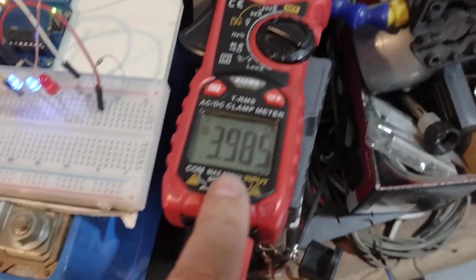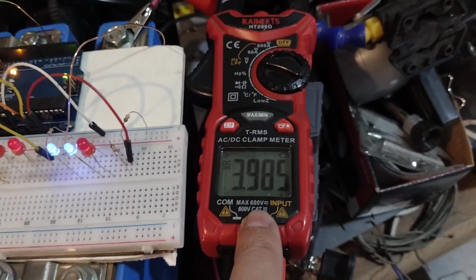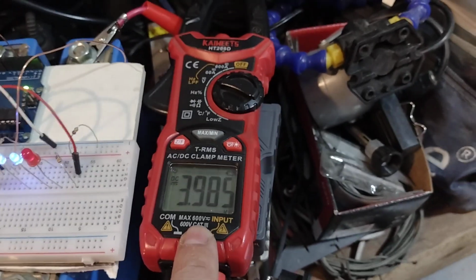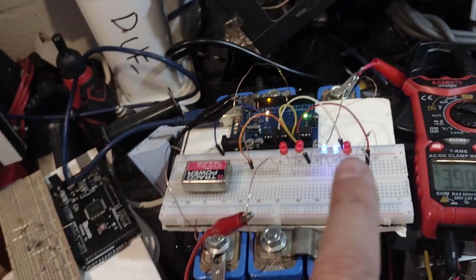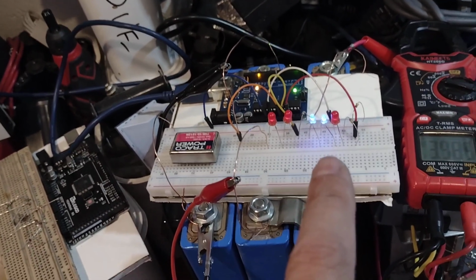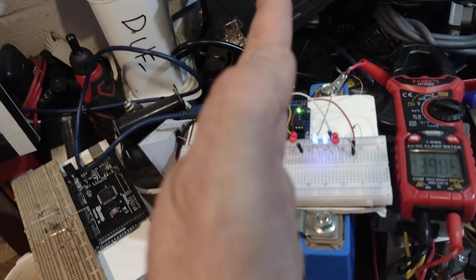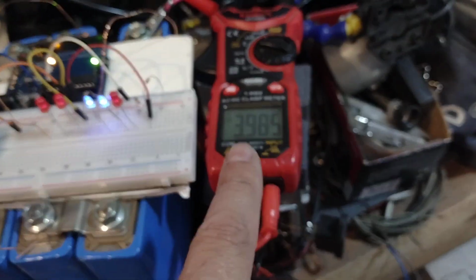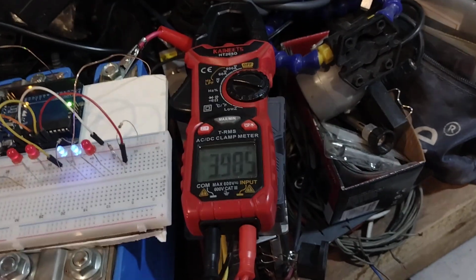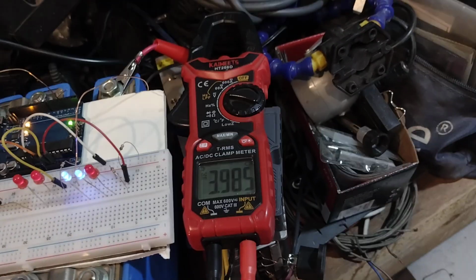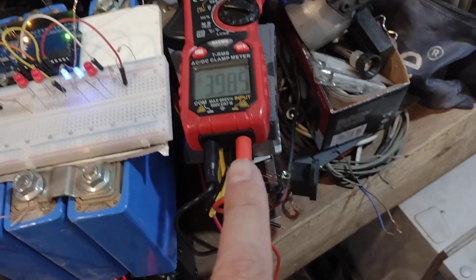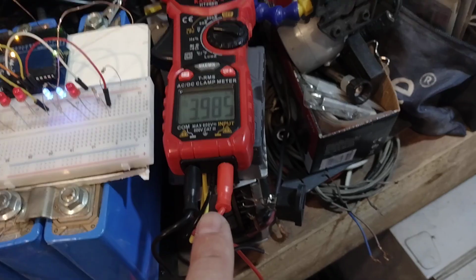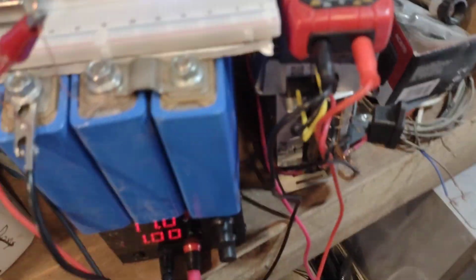That's actually almost 4 volts, right? So I can probably raise it, if it's 3 cells and you're presuming an equal voltage increase across all the cells, then you're talking about 0.2 volts. To be honest, that's actually the voltage I want. That's the target voltage for the pack. Each cell should be at 4 volts. I don't know, but that might slightly overcharge it.